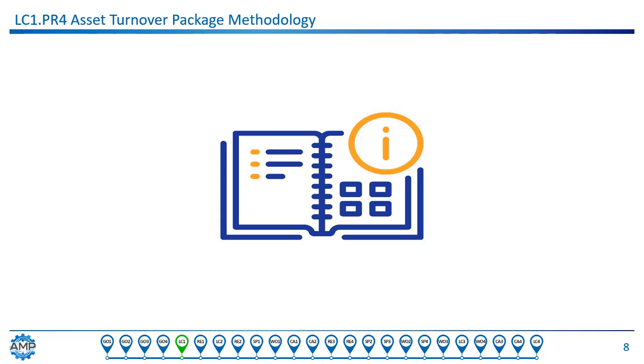Turnover package information collection, organization, storage, and control processes should be established and enforced. There's often a ton of data generated over the course of a large acquisition project, and without firm control over its flow and format, turnover packages will not magically appear someday after the project is over. They're evergreen documents too. Turnover package update and revision processes should include communication of changes to asset owners and maintainers. Turnover package acceptance should be integrated into the asset acquisition project plan and execution as a stage gate for project closeout. No complete turnover package, no final payment, right?